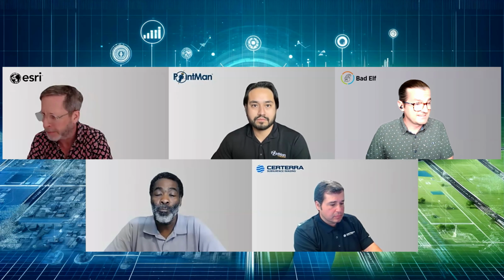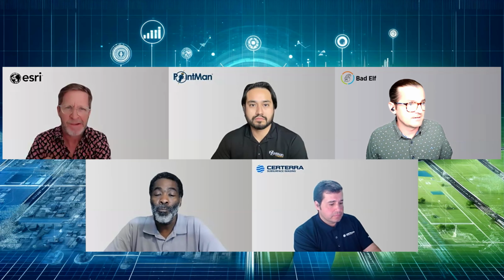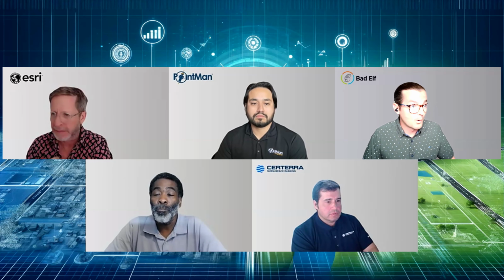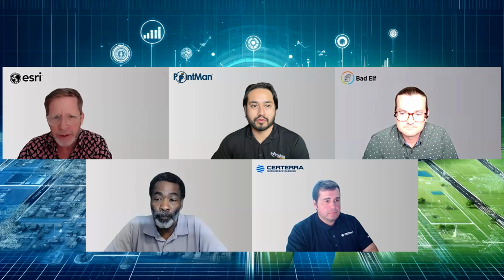What was the PDOP? What was the RMS? How many satellites? What was my baseline? You know, the hope would be that with somebody like Kevin on staff, Kevin's going to teach those people maybe how to check in, right? So checking in at your location at the beginning of your job and at the end of your job. But the idea is it's now easy enough that we can teach more people at your organization to collect that data confidently.